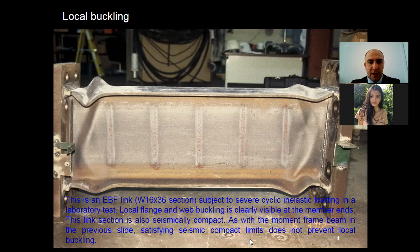Here is another example of local buckling, in this case in an eccentrically braced frame, EBF, with a wide flange beam, a W16x36 section. The specimen was subjected to severe cyclic inelastic load in a laboratory test. Local flange and web buckling is clearly visible at the ends of the member. So you can see it.